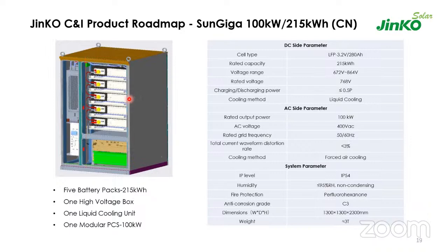That is why people tend to use DC coupled systems, more specifically as an input from solar PV power plants to these DC cabinet solutions, where PCS is not required. But if PCS is in place, definitely you'll go for an AC coupled system.